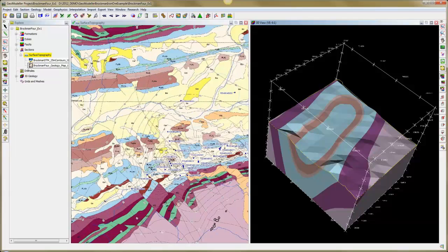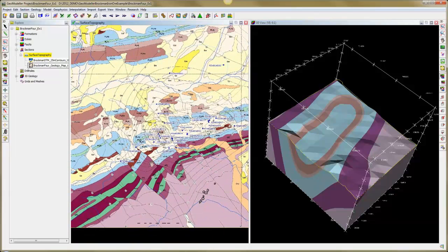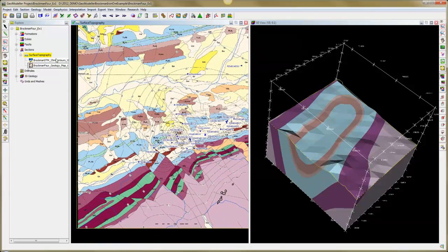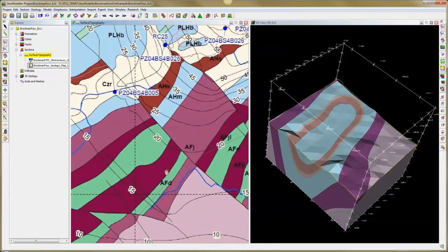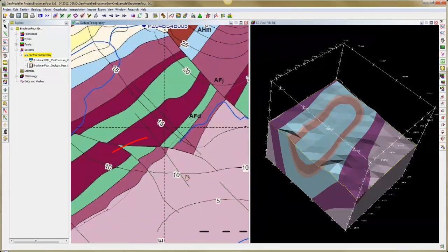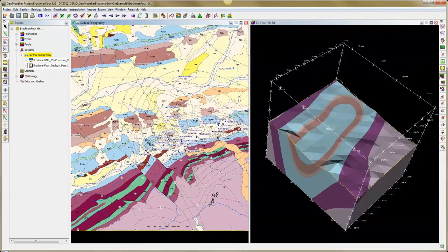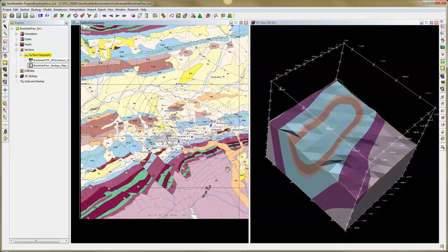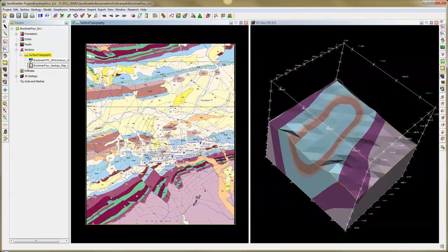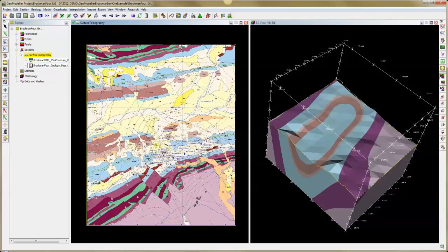So if you look at the geological map, you can see that we have a fault network. And the next step for us is to digitize those faults. So we've got two types of faults in this map. We've got infinite faults that go through all the area of the model. And if I zoom here, the finite fault that stops before the end of the model. So what I'm going to do is open another step of our project over here below,